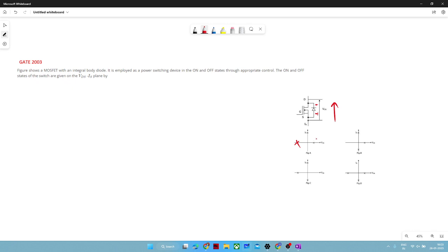Okay, and as we know that either MOSFETs or BJTs or IGBTs, they block the positive voltage if you supply it across drain to source. So if we see from the graph, the typical characteristics of power transistors are they block positive voltage and they are unidirectional devices.